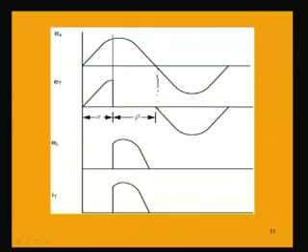That means it is following the supply voltage only till the point where it becomes 0. This will be 0 only after this point. So, from this point again the thyristor stops conducting, and the voltage across the load will be 0.